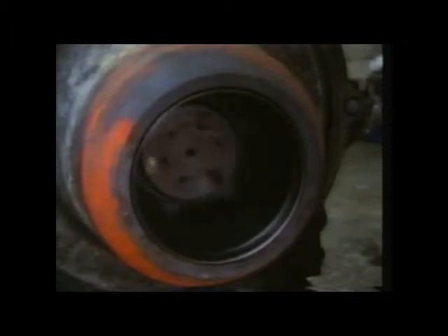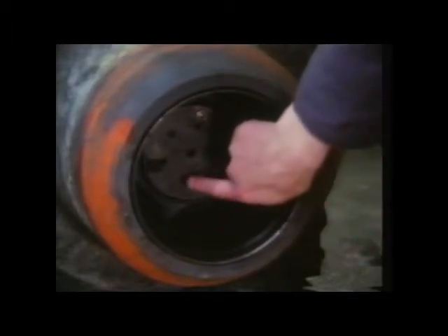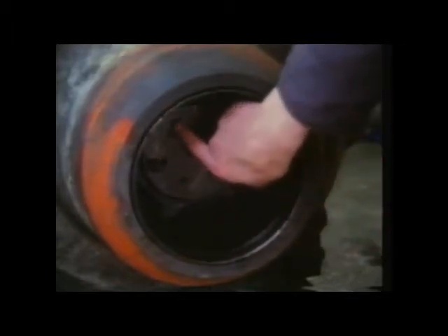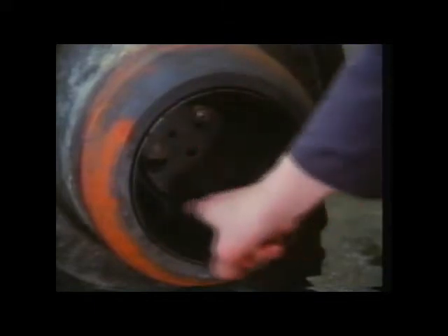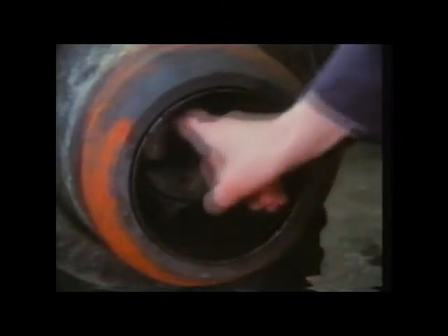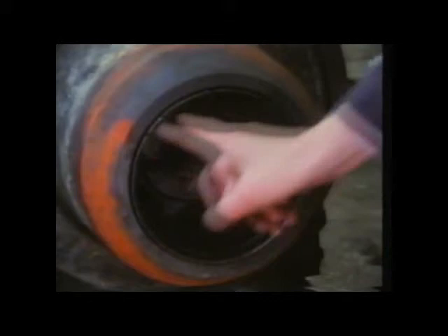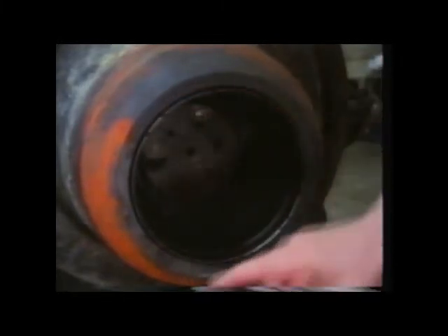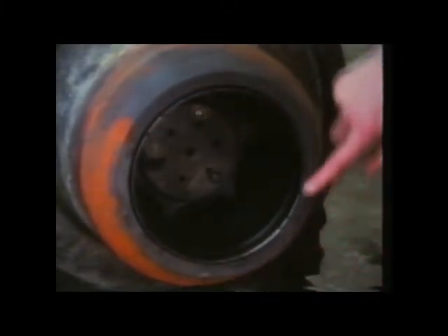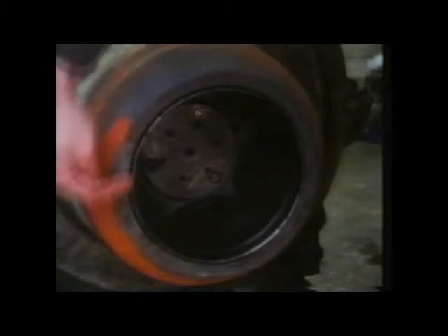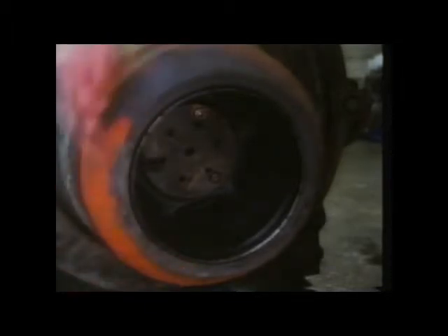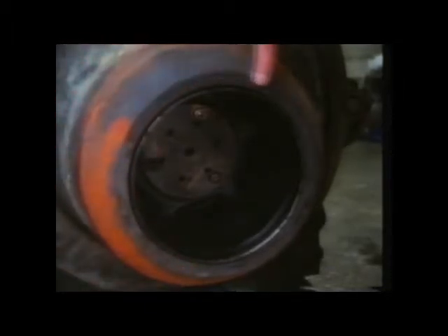In fact, a special burner has to be used at the plant. The liquid sulphur comes out through the holes inside this big rotating cup, and as the cup spins, it's spun out around the inside, like this. When it reaches the rim, the liquid sulphur is broken up into tiny droplets by air blowing out through this circular slot. The tiny droplets burn very rapidly in the air inside the big box in which the burner is fixed.